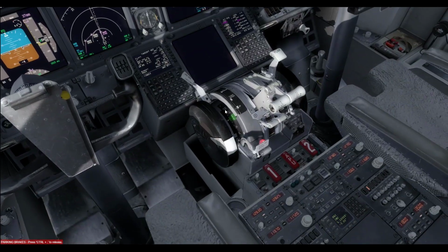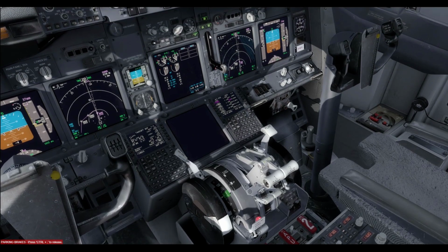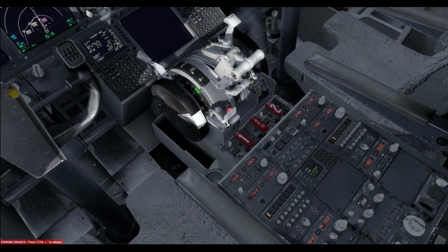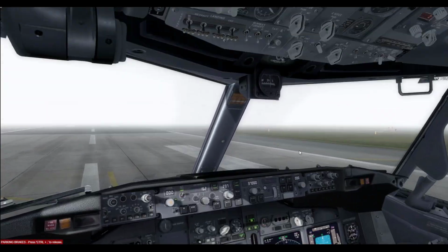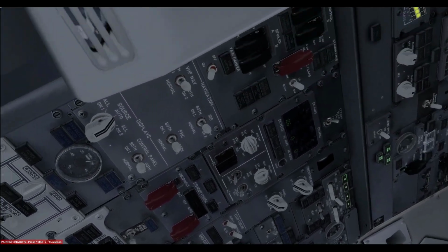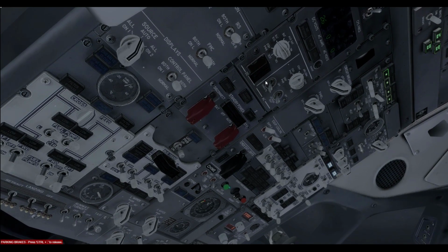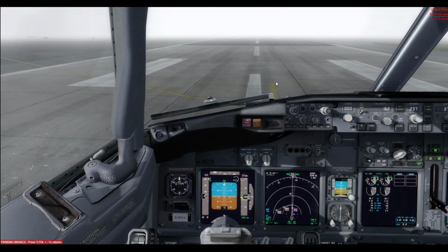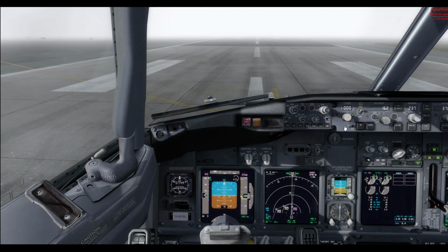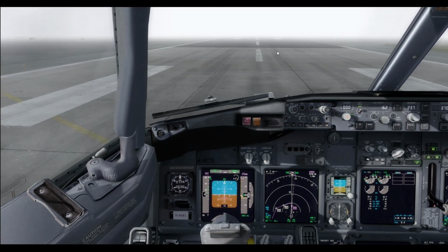So, quick check. Trim is set. Flaps are set. Auto brake is RTO. We have the transponder, the weather radar, the terrain radar, all of the lights. And that is it. No warnings on the overhead. Perfect. We can go. So, start your stopwatch, your own stopwatch. Advance your thrust levels to around 60%. Release the brakes, and once you go past 50, press on this click spot here.